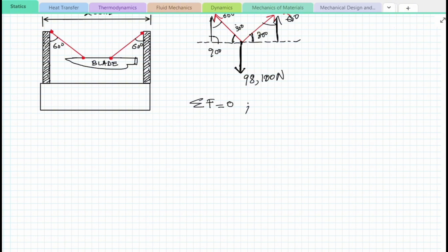So for tension on the cable, since those are facing the positive y axis, that will be the y component here of that tension. So that will be T sine 30 degree. Since Ty is the opposite of the 30-degree angle.